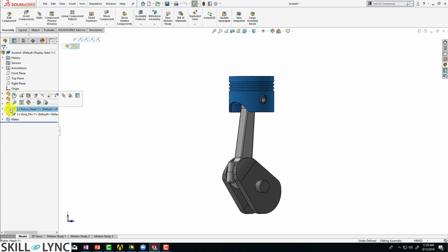The first component is your piston, and the piston is going to be constrained so that it just moves up and down along a particular axis, which is the piston axis. Finally, we have the connecting rod, which basically connects the piston and the crank, right? And because of this connection, the connecting rod is going to have both translation motion and it's also going to be rotating, right? So in this entire assembly, the connecting rod is the one that's going to have the most complex motion.